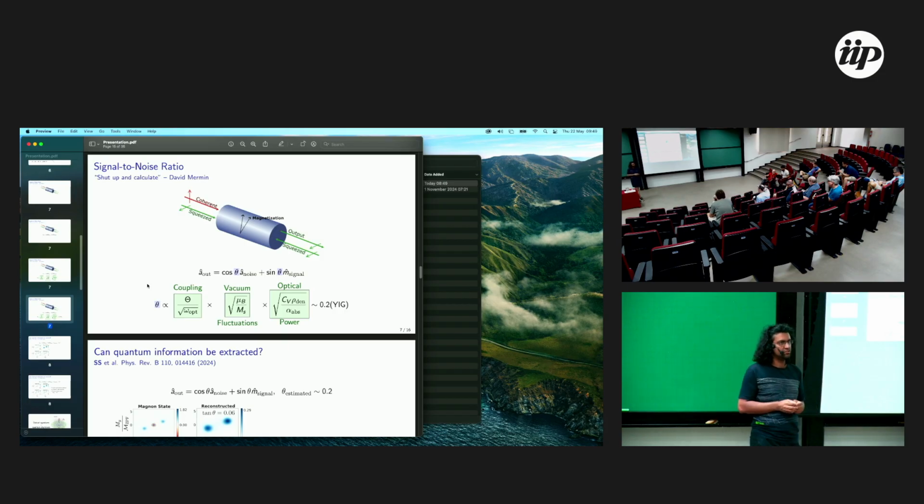Well, the reason I'm asking is that when you demodulate, you have some bandwidth in your pulse, and then you imprint onto it, and those things become convolved. So your frequency resolution depends on the length of your pulse. Yes.